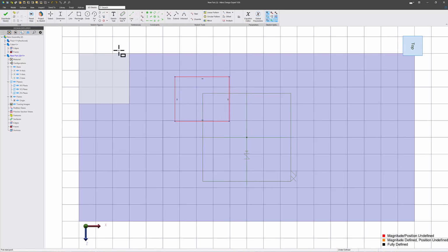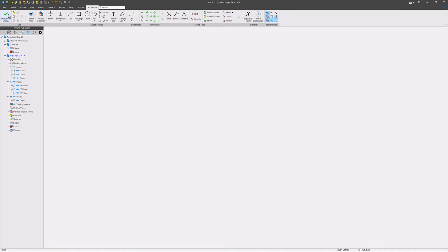And I can make a rectangle. I'll say that I want to be 0.2 away from this wall, right? So I'm using the elements, the other parts of my assembly, to start defining this. We'll say with 1.25. And then where am I not constrained? Of course, I'll say maybe equal here. And I'll give this something like 4, and we are good.